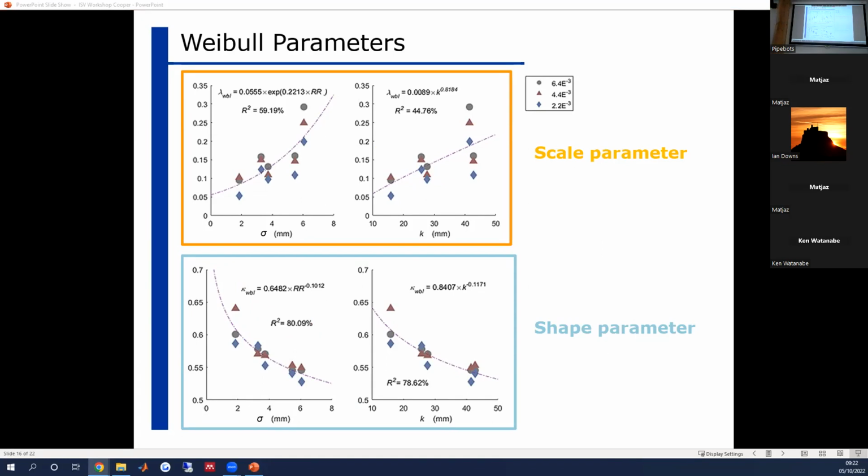Now, if we take those results together, what it's showing is as we increase the roughness, those drag distributions are getting much wider. And also we're shifting everything to the right-hand side. In other words, we're getting a higher proportion of areas experiencing higher drag as we increase the roughness of the eroded soil surface. Sorry, we're running very short on time.